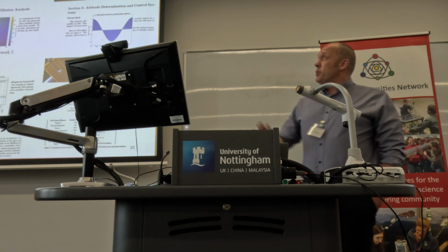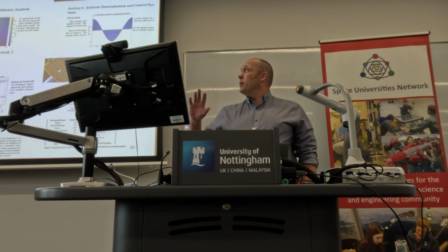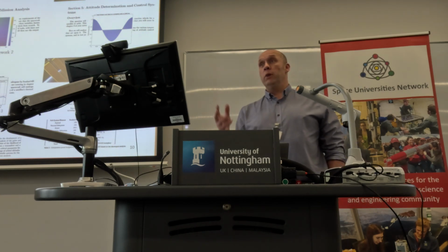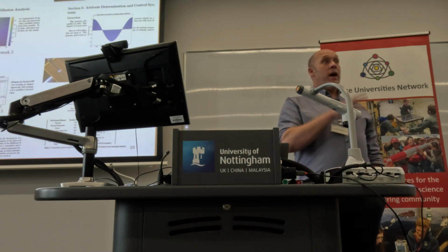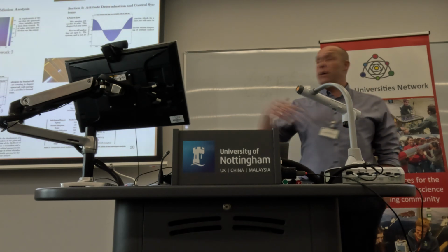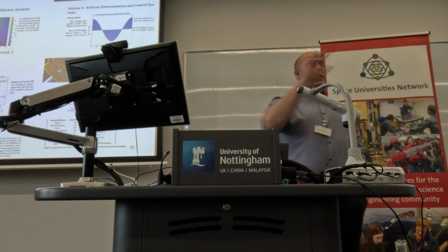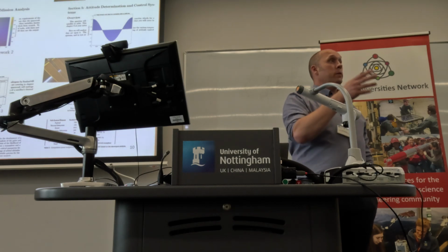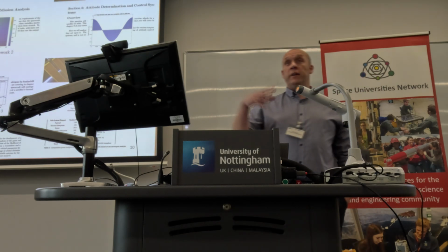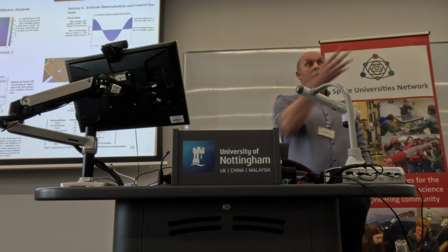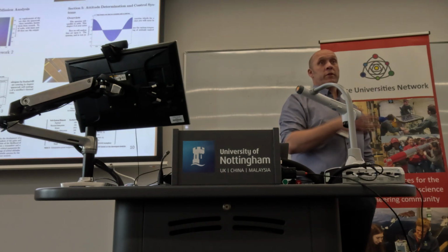And the output was a series of 5 tutorials, and each one allowed them to do some analysis, do some modelling and coding, get an output, and then make an engineering decision off the back of it. So the first one was a launch propulsion sensitivity and mission analysis. In that sensitivity, they worked out what thrust they required in order to achieve the mission objectives, how much fuel it needs, and then made a decision. And the output was how much mass they had to launch with on the spacecraft.